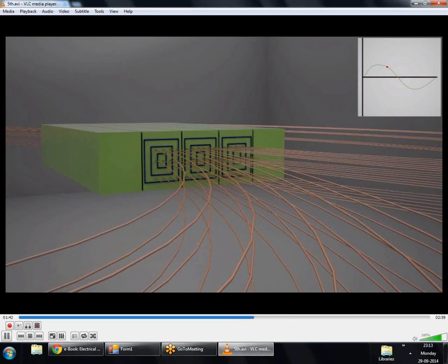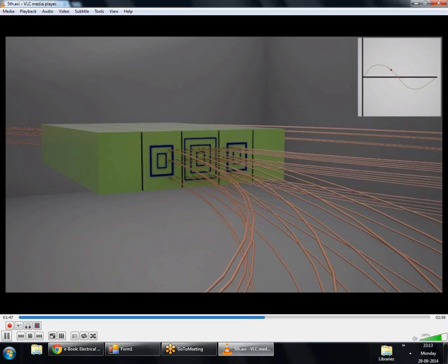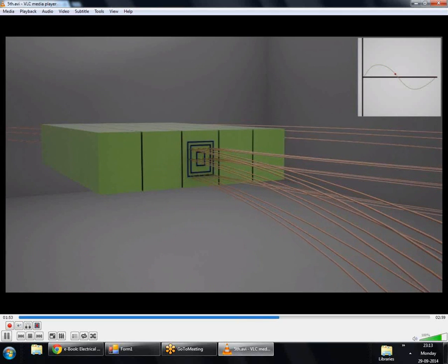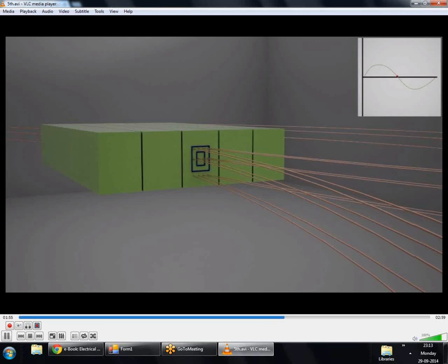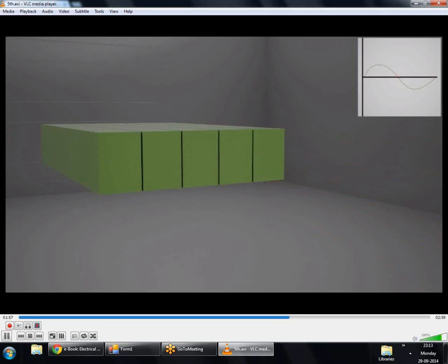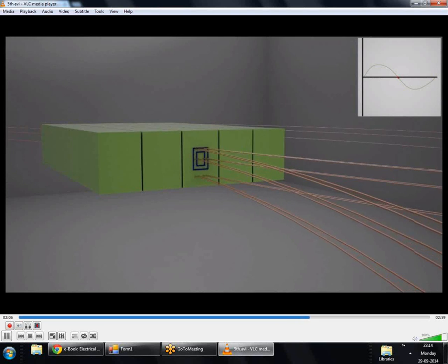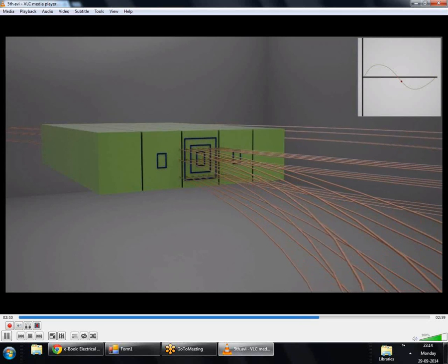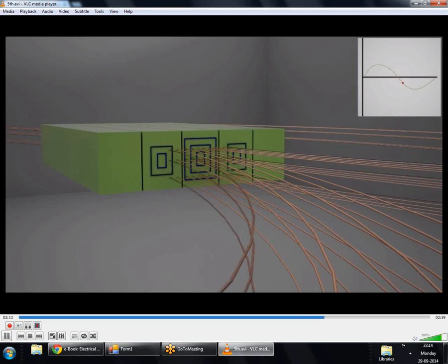My applied magnetic field remains constant, but due to the increased resistivity we have lesser current flowing through the ferromagnetic material, and as a result we have lower ohmic losses, or the I square losses. So lamination is one of the most important techniques to reduce the eddy current losses in our ferromagnetic cores.